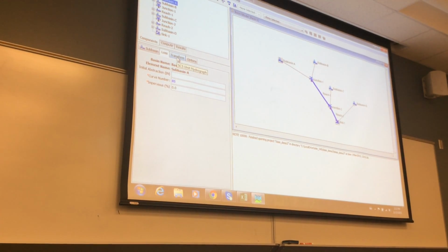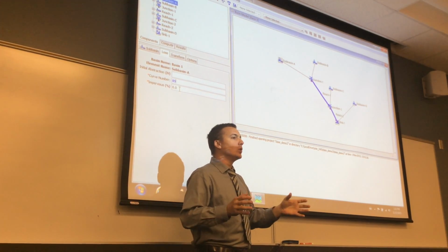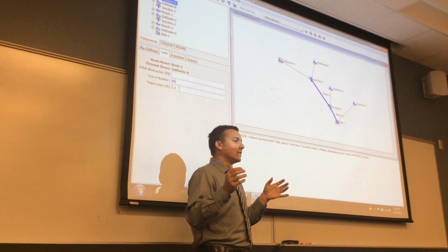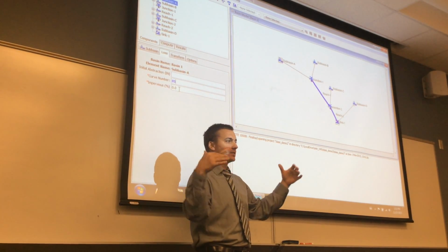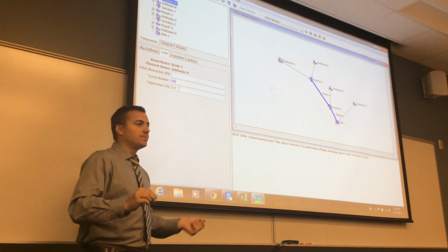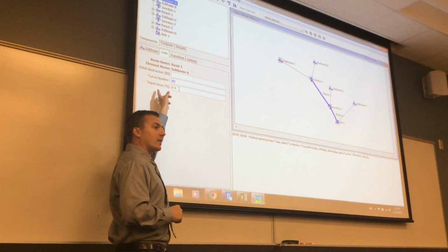Now I'm going to do a transform using the SCS. You do not need to put in impervious; 0 is fine. What impervious is doing here is adding to it. So if you know you have a region of your sub-watershed that's impervious, you can say 20% is impervious and the rest is curve numbered. We'll go with 0 everywhere for now, because we're adopting curve numbers in a way that incorporates that.